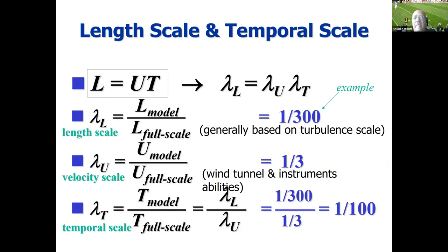And I think this thing which Rindam mentioned, about more than a decade ago, our group and Polytechnic Milano tried to dissect the power spectral density of wind into 2 parts, the lower frequency and the high frequency. And we did that theoretically in order to model the effects of turbulence on bridges, because it was not done before computationally.